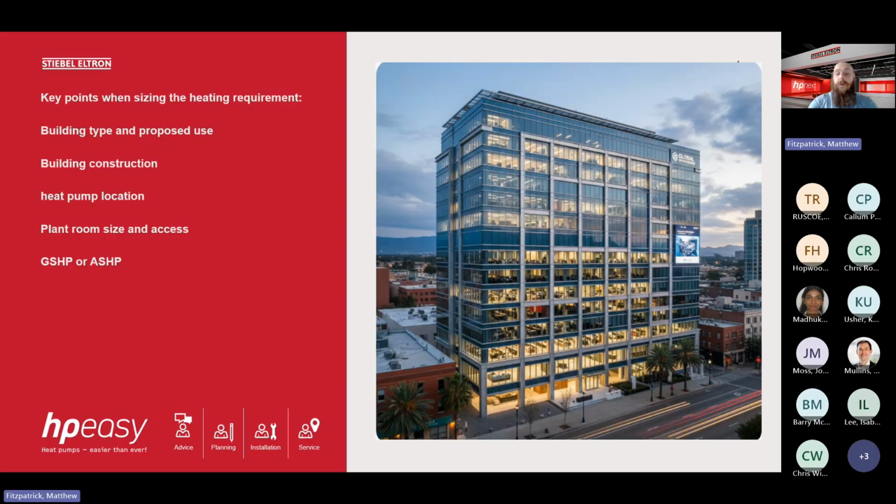So some key points to take away when we're looking to size a heat pump for a commercial property. First of all, we need to look at the building type and the proposed use of the building. An office building which has been renovated from a retrofit property from the early 1930s, 1940s, or for example, the old mill style buildings that have been renovated from the late 1800s will not only have a greater heat loss requirement than a modern building, but there are other aspects that you will need to look at, such as ventilation.